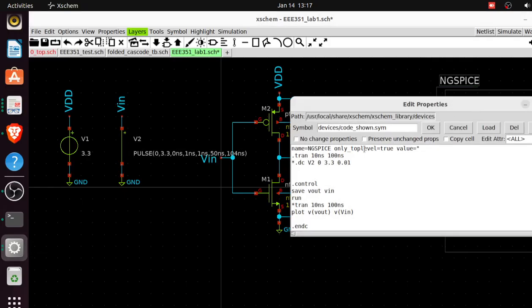For mine, I only specified two values, the step and the stop. The start was not specified. If you don't specify the start value, the default value is used. The default is 0, so it will start at time 0. So I left it that way.